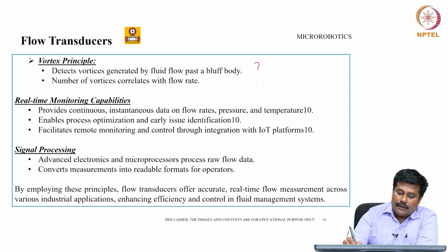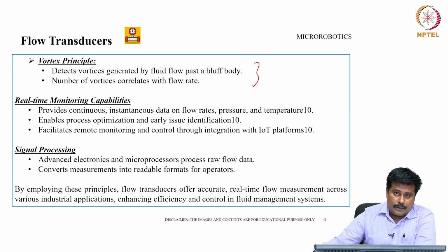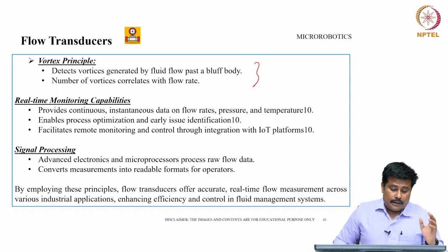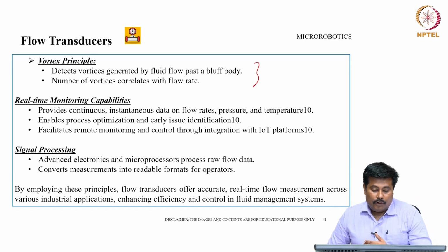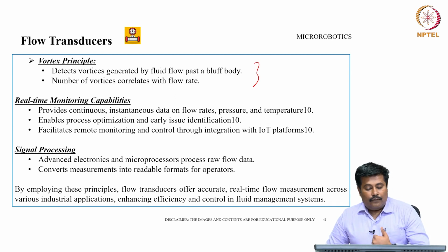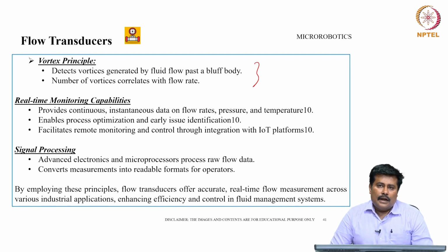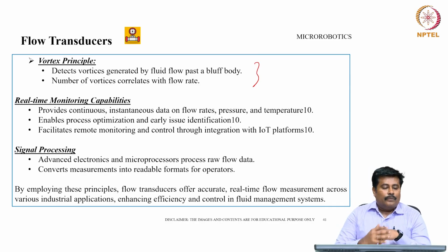Next is called the vortex principle. From the vortex principle point of view, it detects the vortices generated by the fluid flow passing a bluff body. The number of vortices correlates with the flow rate.